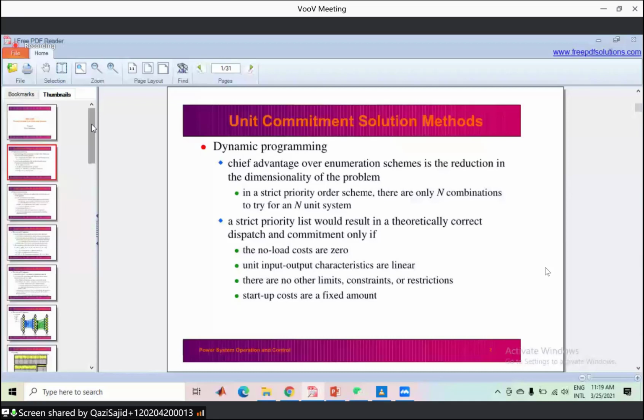Unit commitment is an operation planning. The purpose of planning is to determine a schedule called the unit commitment schedule, which tells us beforehand which unit to start and shut down during operation over the specified time, such that the total operation cost for the period becomes minimum. Unlike economic load dispatchment, the objective of planning is not to distribute the load in time between the units already running in such a manner that every instant varying operation cost becomes minimum. So that is the main focus of unit commitment: it is an optimization process to determine the operation schedule.